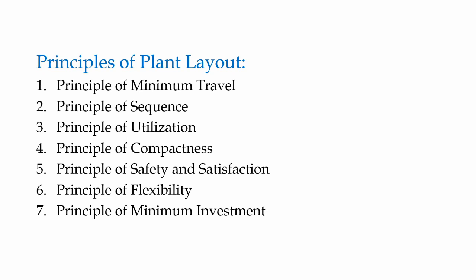Then coming to the principle of flexibility, the layout should be as flexible as possible in order to accommodate new equipment or machinery or of higher capacity machinery in case of change in demand or change in product design or process. Then principle of minimum investment. So as there is some investment in designing the plant layout as well as establishing the plant as per the layout, the investment on the plant should be minimum. So keeping in all these points or principles in view, we have to proceed for designing the plant layout.